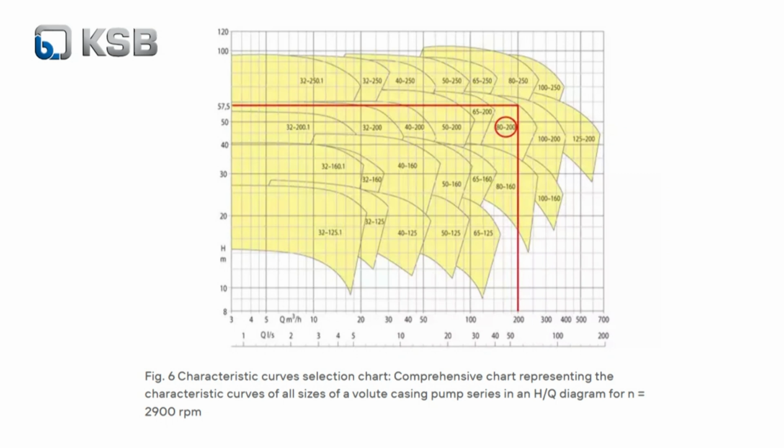Pumps, centrifugal pumps. Everyone selects them. How do you know which pump and what efficiency and things like that? So go to a vendor. This is KSB. A lot of people sell centrifugal pumps, based on the flow rates and the head. Y-axis is the head, x-axis is the flow rate. These are the curves for various pumps. And this is how you select whether you want pump 32 or pump whatever, 200. Right? Because for whatever application you're doing, if you've done the sizing correctly, you know your flow rates and heads.